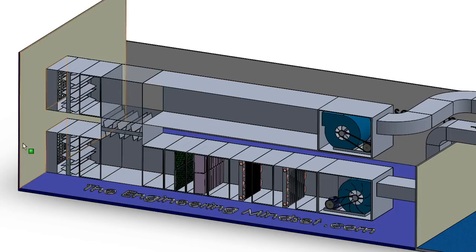Obviously there will be some fresh air. It's usually about 10% of all the air going around the system has to be fresh, but there will be some set points in the BMS, the building management system, which will control all that, and the controls experts will set that all up. But we will look at some real examples of this. Not in this video. In this one, obviously, we're just covering what's happening inside the AHU.